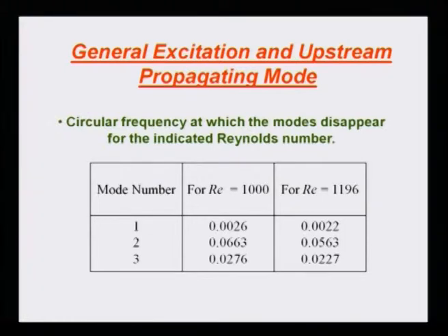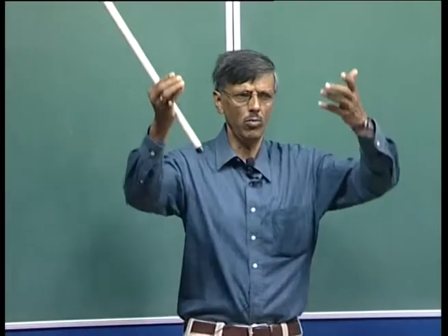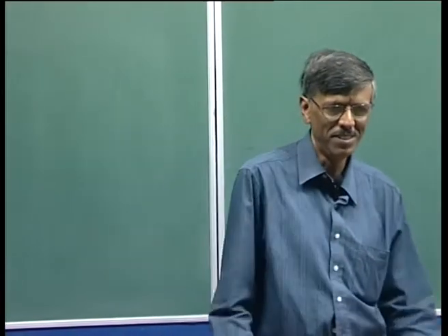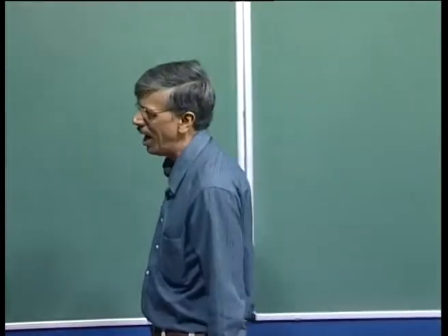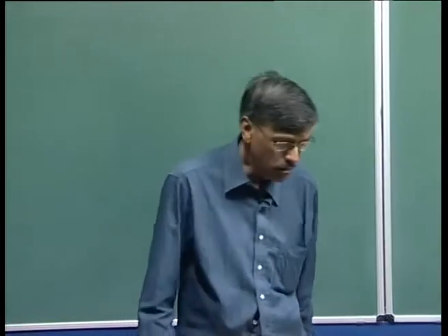They also vibrated the bump at a low frequency, and a very strange thing appeared. Once again, people did not see any wave per se, but they saw that the whole shear layer went up and down, as if the boundary layer is breathing. That is why these are called breathing modes. As if the whole boundary layer is heaving up and down.